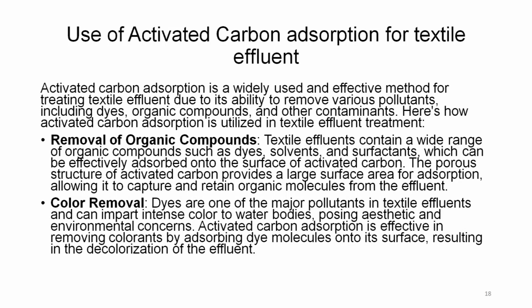Color removal. Dyes are one of the major pollutants in the textile effluent and can impart intense color to water bodies, posing aesthetic and environmental concern. And time and again, whenever we talk about dyes and the color of the dye, we talk about this. Activated carbon adsorption is effective in removing colorants by adsorbing dye molecules onto its surface, resulting in the decolorization of the effluent.